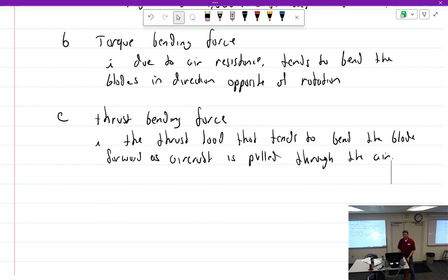I was talking to a prop shop. They said on really hot days, people doing that, you'll ruin the blade. So, if you're going to do it evenly on both sides. How come your propellers curve backwards? That's a special thing. I will push on my blade if I absolutely totally have to, and I have no other choice to move my airplane, but I'll only push right about here, right next to the hub.